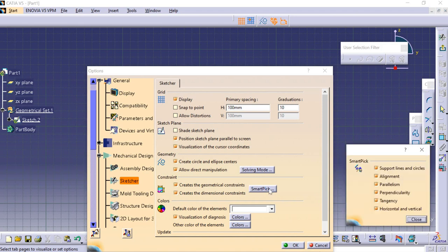So as you create more and more elements, smart pick detects multiple directions and positions and more relations with existing elements. This may lead to confusion due to the rapid highlighting of several different detection possibilities as you point the cursor at different elements in rapid succession. So consequently, you can decide to filter out undesired detection. This smart pick tool shows how to use it.